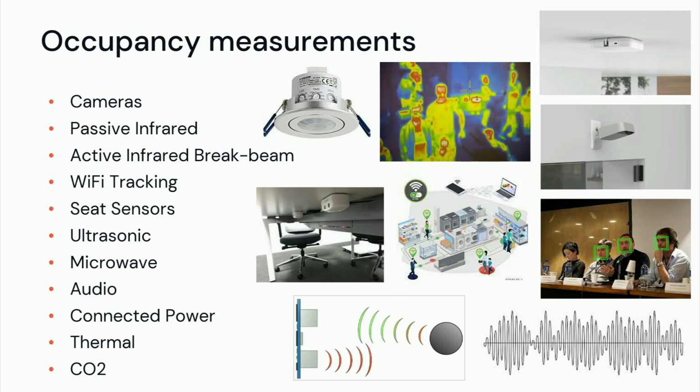In a space, people generally breathe out 0.05 meters cubed of carbon dioxide an hour. And we can use this over time to indicate how many people have been in a building or how many people are currently in a building. It's a very, very slow lag, but it is an indicator of occupancy. So if we can work out where people are, we can make our buildings safer.